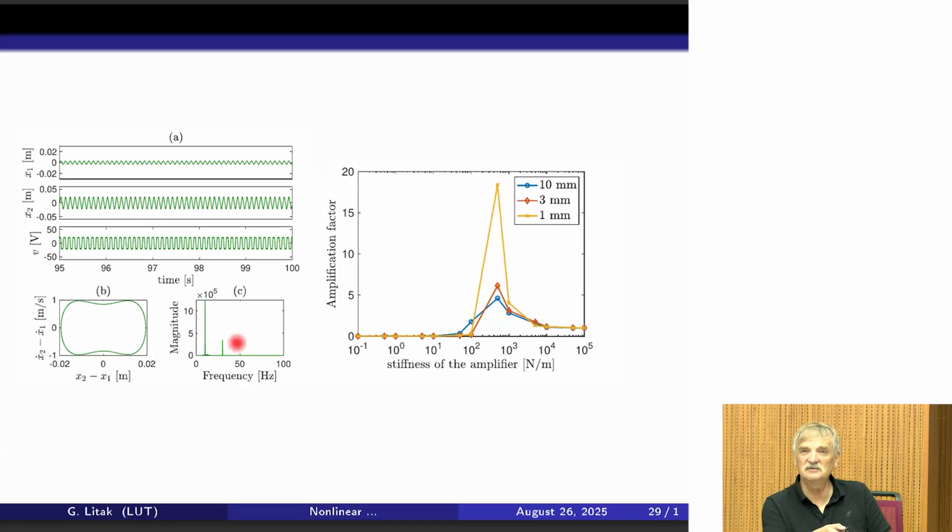But here it is the solution. I told you that the large amplitude nonlinear response could have some leading frequency like the excitation frequency, but a second peak is appearing, and the second peak is much smaller. However, there is deformation from the circle. It's not a circular response in terms of a phase portrait, telling us that there are some nonlinear effects inside this time series. Time series like this is x displacement against the velocity, the velocity against displacement.